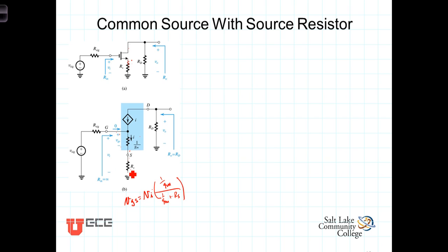Finally, we're going to omit the early effect resistance, the little R0. That resistance would be connected between the drain and the source and significantly complicates the analysis. It turns out that R0 doesn't have as great of an effect in this configuration with the source resistance there, and so the results that we'll get are still going to be valid to a large extent, not affected by neglecting that early effect resistance. So with these observations, let's go ahead with characterizing it.